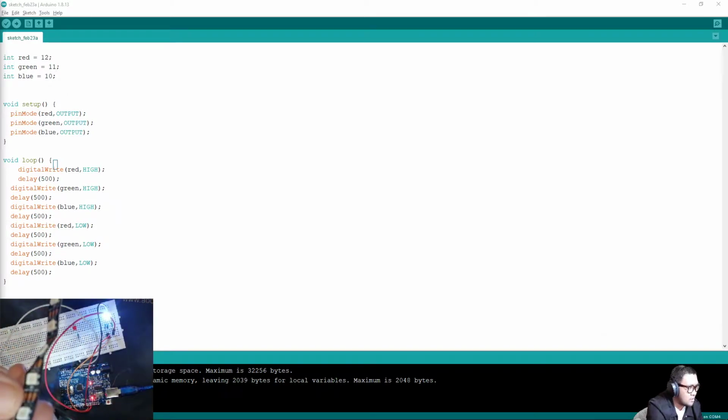Okay. So you will notice that there are several LED bulbs in there that are capable of outputting three different colors. So for each LED bulb, we will be needing three resistors. Also same for the RGB LED bulb. Because it is governed by three colors, each of these colors makes use of one resistor. So we will be needing resistors, specifically 220 ohm.